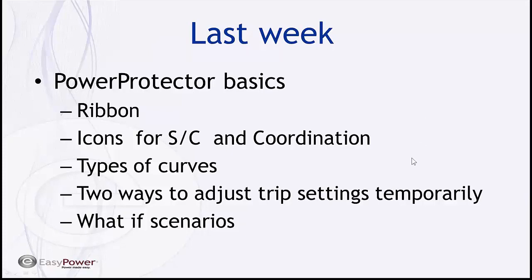We also talked about two ways of temporarily adjusting the settings. One is to click and drag the curves themselves, and the second is to open up a temporary dialog box for that element and make adjustments or look at the impact on the system if we considered using a different size or different characteristics of device or even loads, a kind of what-if scenario analysis.